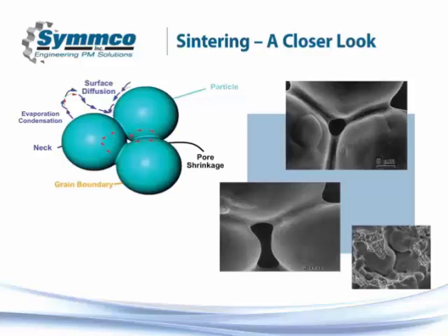That's quite high in density and typically achieved with some newer technology materials, primarily a warm compaction process where we actually heat the tooling to help us get to that density. Those densities create the higher mechanical properties needed on many of today's components. So density does drive strength, and we're going to take a look at that as we move forward.